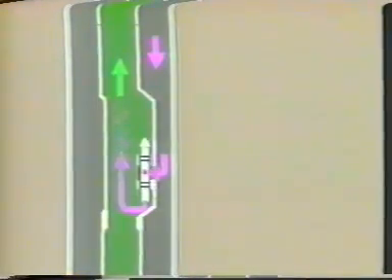The side pocket has polished packing bores machined above and below the ports and a locking profile in the upper end of the pocket. The major advantage of the side pocket mandrel is that when these devices are installed in the side pocket, full tubing bore is maintained.